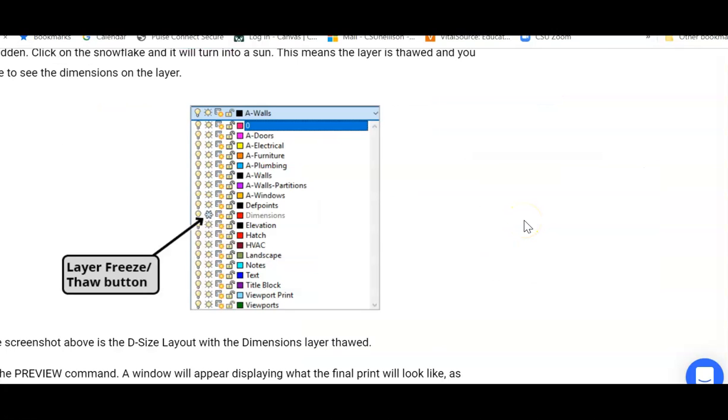The other thing we want to do is draw our elements on a specific layer, because what's going to happen potentially is that we are going to merge our drawings with other people's drawings, meaning our drawings are the civil or the structural drawings, and we might overlay the architect's drawings or the mechanical drawings. And so we want to differentiate what we've drawn from what they've drawn. And so we're going to give our line weights and our layers a name.